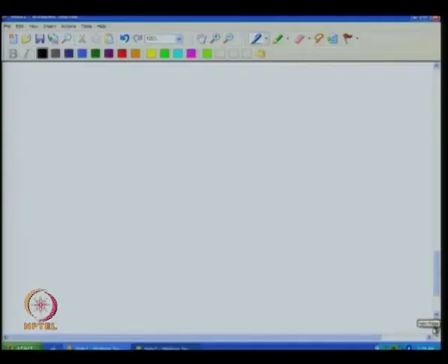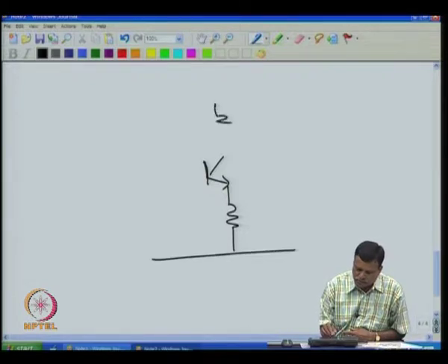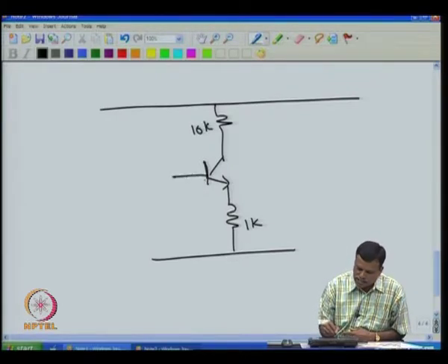But then when they tried to use this amplifier for DC applications, this amplifier started giving many problems. For example, if I try to see how to use this for DC amplification, then immediately we get into many problems. Say I have the same transistor amplifier, and I want a DC gain of 10. What I do is put this resistance, then apply the voltage, and I know that I have a gain of 10, so I put this 1 k and 10 k, a ratio of 10, then the gain comes to 10. Then I have to bias this, because I want to keep this one at the midpoint 7.5, so that when the signal is applied, this will go up and down.